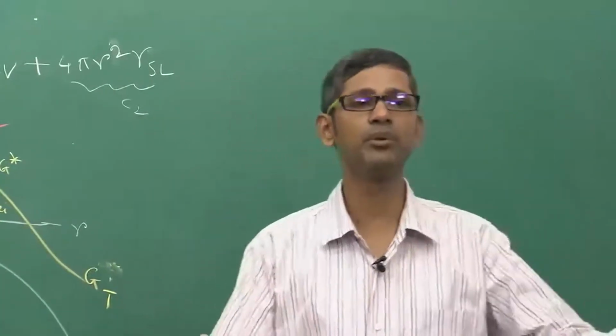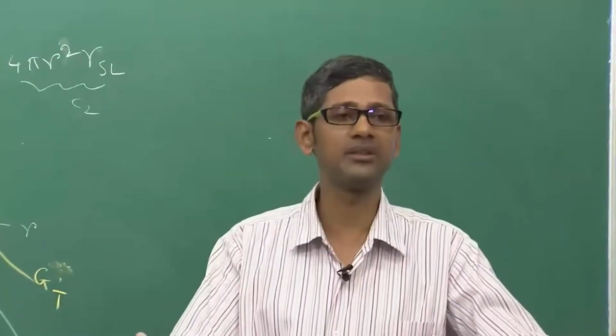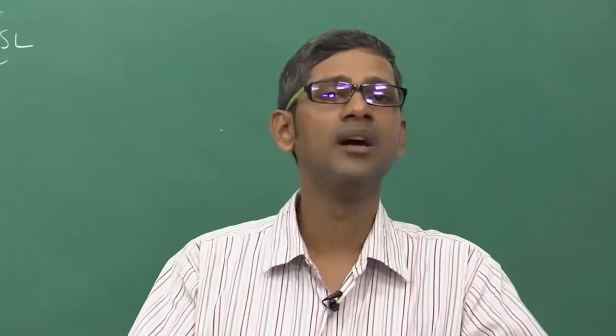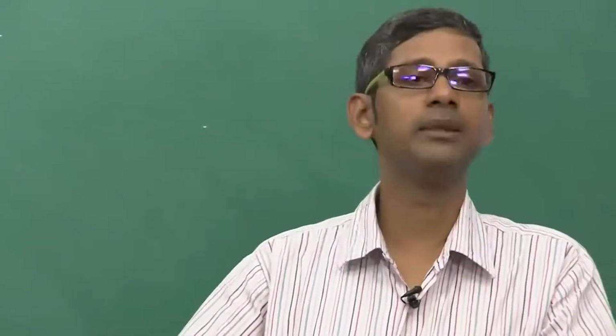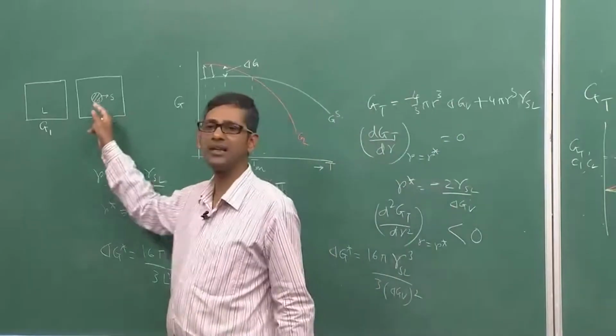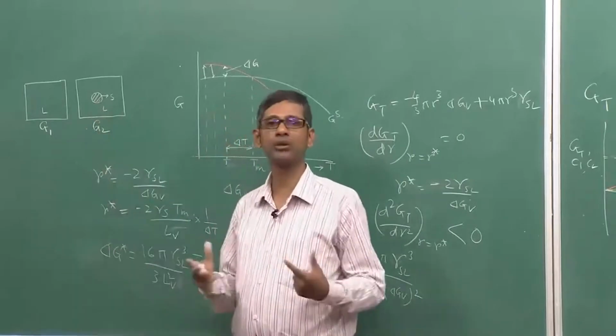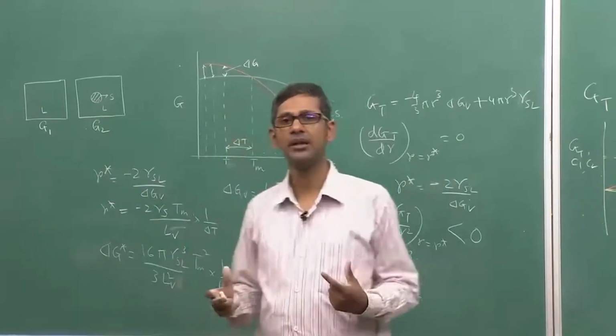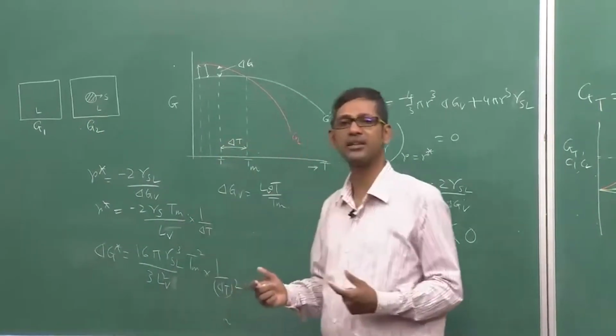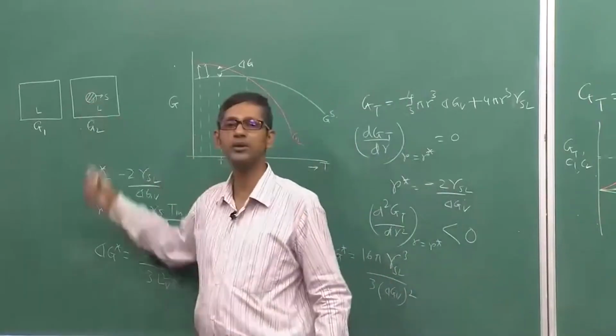When I am talking about solid to liquid and liquid to solid transformations, the only thing I am assuming is what? There is an interface between solid and liquid, correct? And because liquid basically cannot take up any shear, consider any volume change because of solidification. It is very clear that solid will be a more close packed structure than liquid, so the unit volume of solid and liquid will differ.